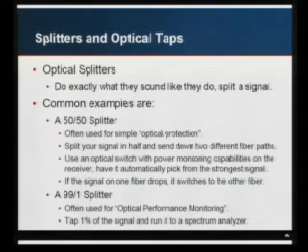And then on the receiving side, you have a very simple optical switch with power monitoring capabilities, and it says which one of these 2 signals is stronger, and it uses that one. And if the signal ever dies, if there's a fiber cut, if there's an issue, it immediately switches over to the other signal. So you get optical protection over your entire spectrum for only a 3 dB hit, losing 50% of your power. It's a very cheap method of protecting a lot of channels, especially if you're using this with WDM, to just optically protect them.